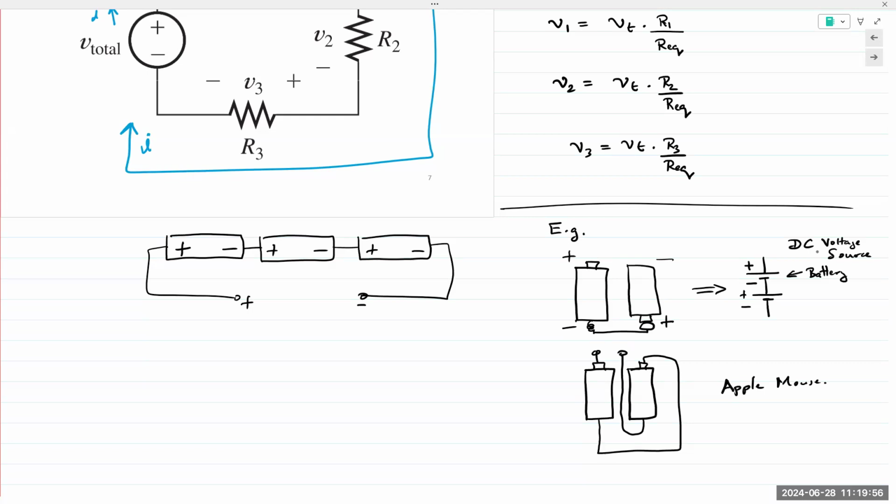That's why it's more expensive. But the logic and the electrical system remains the same. You have two voltage sources connected in series, and the voltage sources connected in series will add up. You can verify it with KVL, you can verify it with Ohm's law, you can verify that system with multiple different ways. Any other questions before we move on to the example?